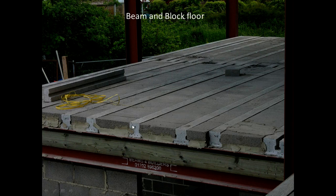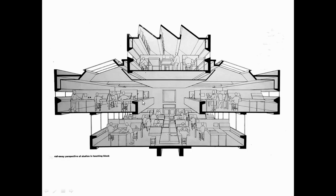What do you notice about these T-section beams? Well, of course, you see these little holes? These are the rebars, the reinforcing steel, which again, as you would expect, is predominantly in the lower part of the beam, taking the tensile load there. So they're cast into the precast concrete beams.